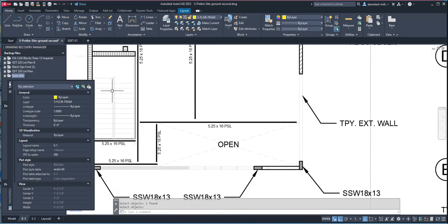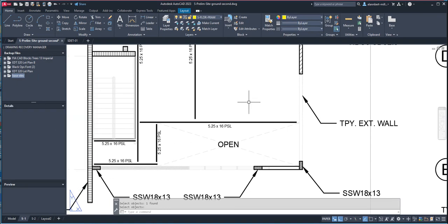I don't see it because of this one. Yeah, there you go. Double click. If this one is a triangle here, then you're in paper space, and you should be only putting text. But if you want to draw objects for your drawing, you should double click this, and you should have an XY here.